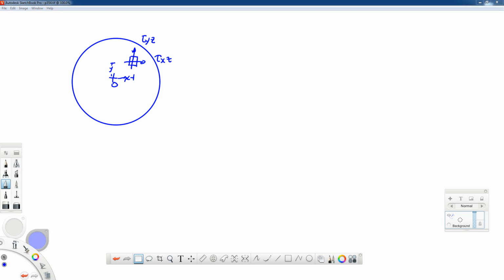So if we were to look at any particular stress state like this, the traction inside the material would be a vector that looks like tau xz in the e hat 1 direction plus tau yz in the e hat 2 direction plus 0 stress in the 3 direction. We have our substitutions that we've made for these in terms of the twist rate: minus beta y G and plus beta x G.